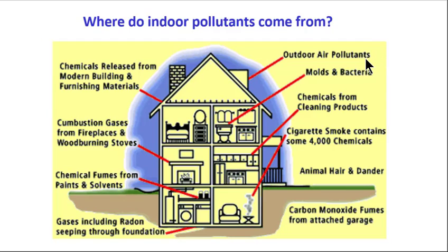Depending on ventilation rates, outdoor air penetrates indoors such that, absent any indoor sources, concentrations of atmospheric gases indoors will match those outdoors. For example, carbon dioxide concentrations indoors will eventually reach around 400 parts per million, the typical outdoor air concentration, assuming that no people, plants, or pets are inside exhaling CO2 and no other sources of CO2 inside are present.